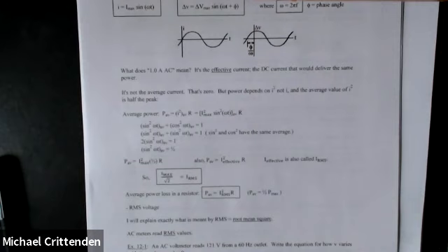If you've got 117 volts at your house, and if we've got 121 volts in the physics lab at the college, it's all good. Just about any kind of electronic product that you can buy is designed to operate. I think they'll go as low as 105 volts before you've really got any risk of hurting anything. And I think you can go at least as high as 130 and get away with it, maybe even 135. So getting exactly the right voltage is not much of an issue.